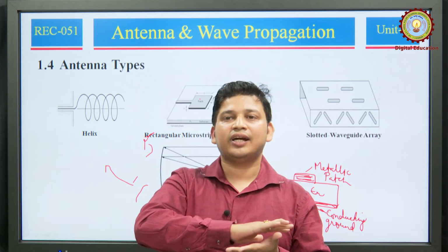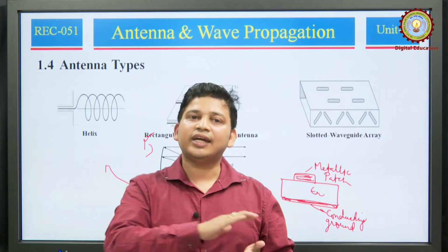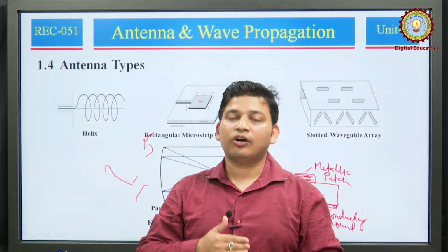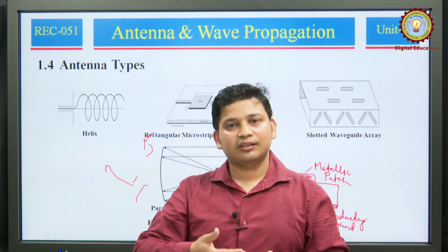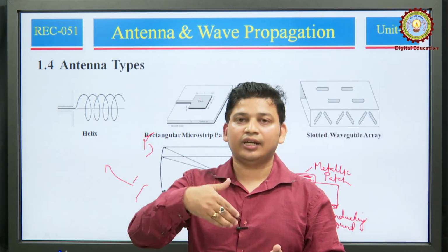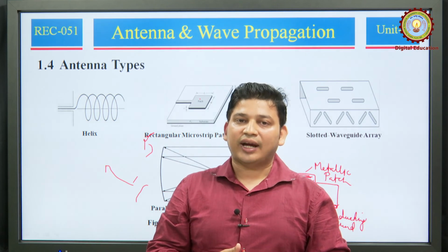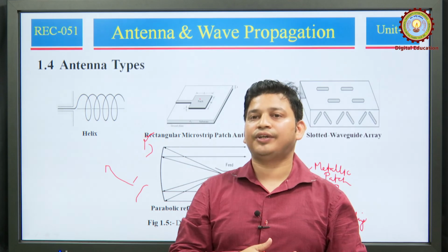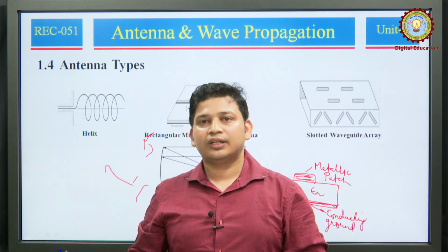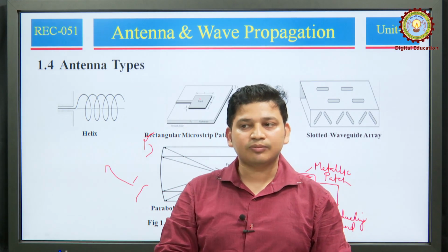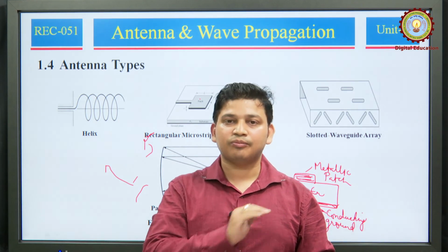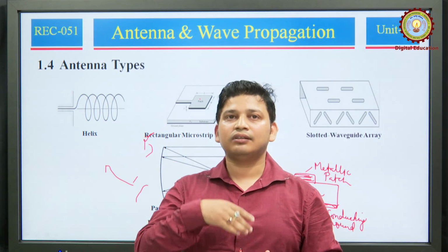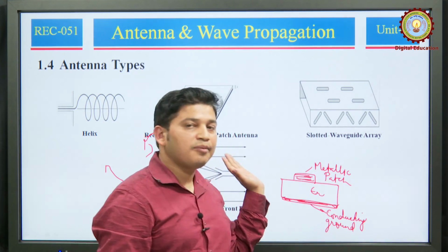So, a transmission line is a poor form of antenna, and leakage of charge requires acceleration or deceleration of charge, or time varying current. Time varying current creates a time varying magnetic field, and vice versa, a time varying magnetic field creates a time varying electric field, hence electromagnetic wave. Second, we discussed the radiation mechanism, how radiation is happening, we discussed briefly the necessary conditions of the radiation mechanism. And last we discussed the types of antenna.